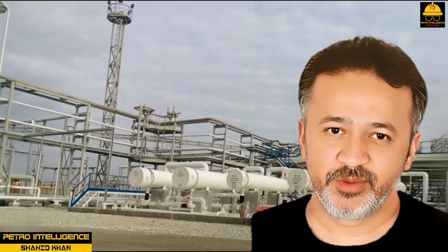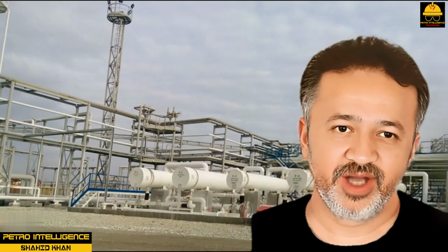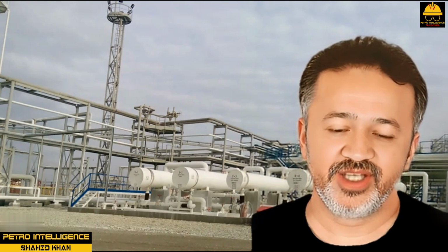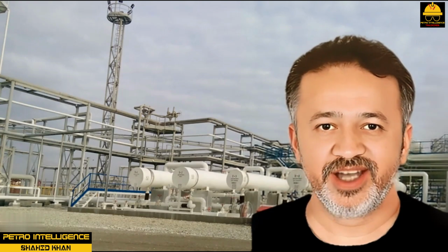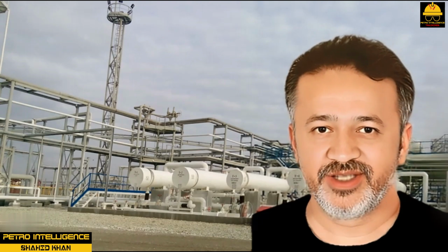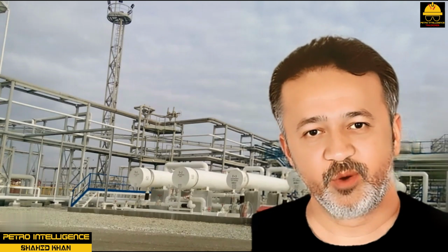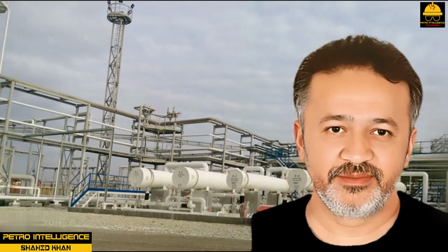Nozzles and accessory parts. Shell and tube inlet and outlet nozzles are sized for pressure drop and velocity considerations. Nozzle connections frequently have thermowells, a chamber that houses temperature sensing devices, and pressure indicator connections. Safety and relief valves are located in required areas around the exchanger.